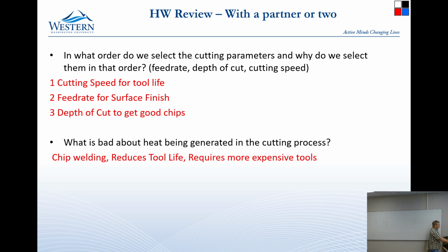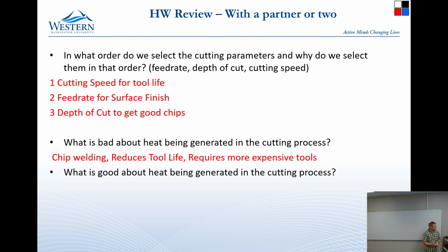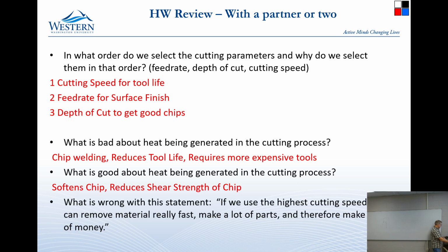What's good about heat in a cutting process? Softens the material. It softens the chip specifically. So it softens the chip, helps the chip to just roll around and curl better, so that it will then cool and break. So that is the primary thing that it does.